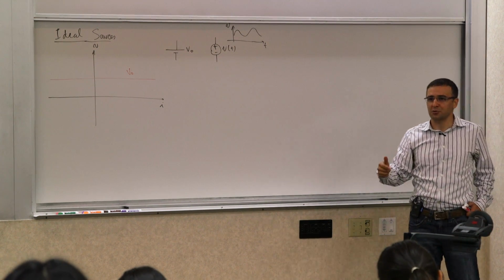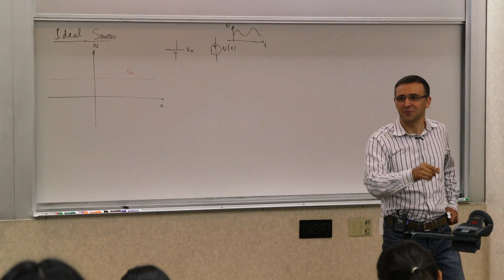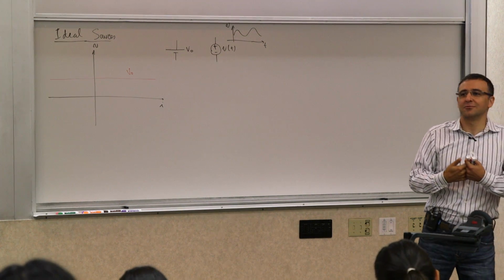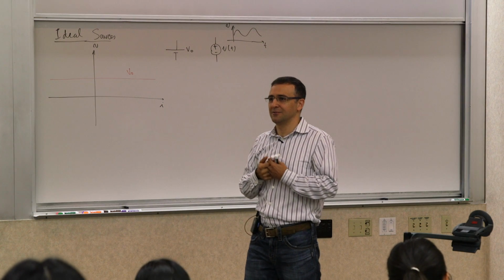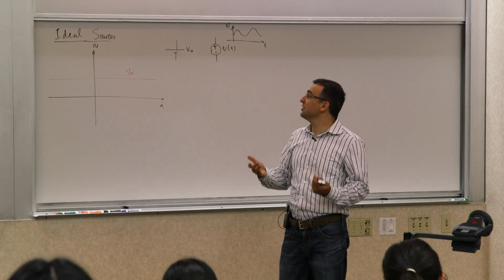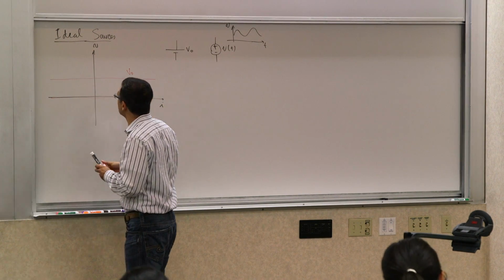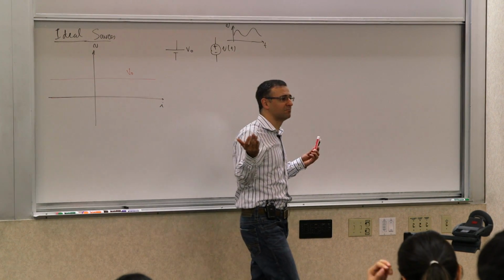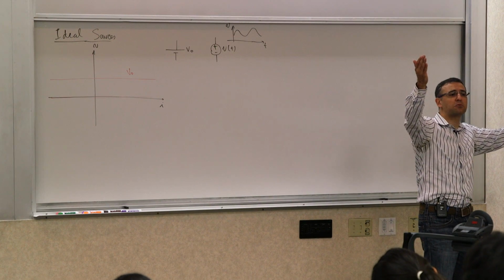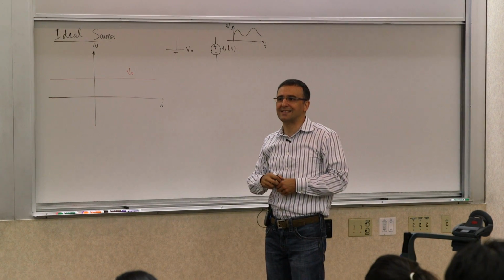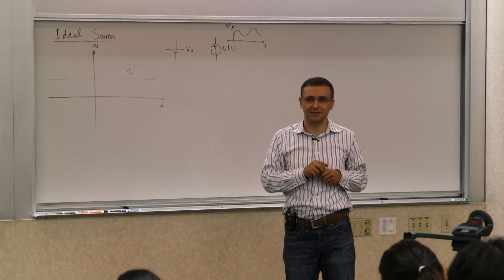I think wire, I say short circuit. So, again, if you want to speak physically, you say wire. If you want to speak mathematically, you say short circuit. Definition of short circuit essentially is this line. A circuit whose voltage is 0 no matter what the current is. Right? No matter how much current you pass through this thing, it basically shows you no voltage. It drops no voltage. It has 0 resistance. We'll talk about that in a second.